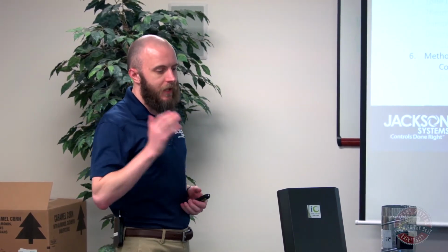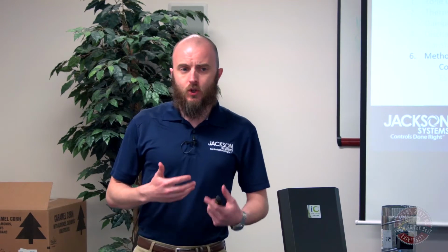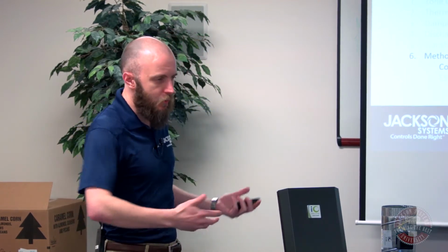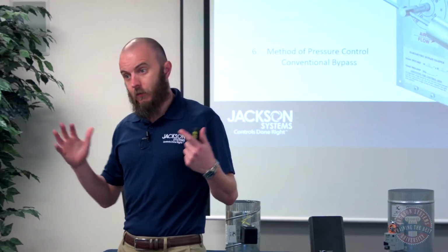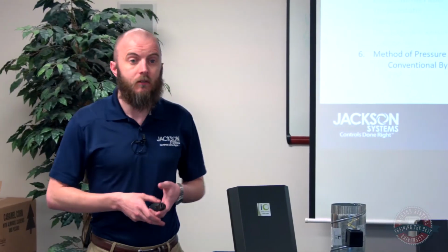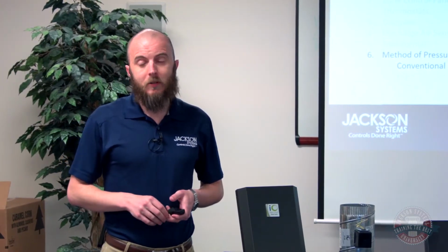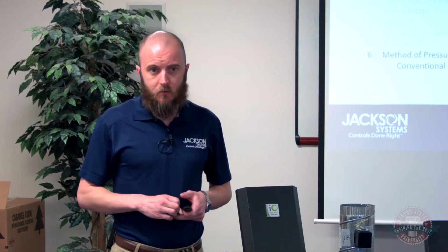You have to at least look at it and address it. In some cases, you may not need to take any additional steps for pressure control. So for example, if you have a 2-zone system and the zones are pretty equally sized, and if the ductwork is a little bit oversized, if the ductwork's 10% oversized or so, you probably don't need to take any extra steps to manage the pressure.